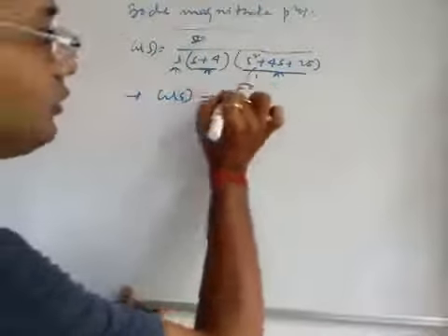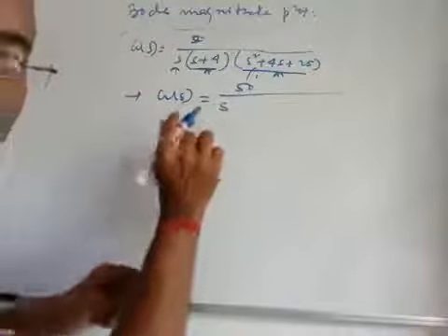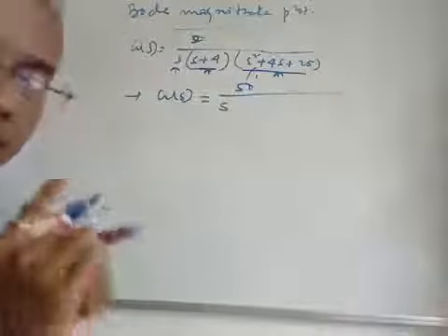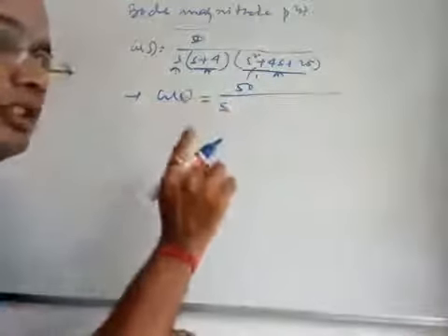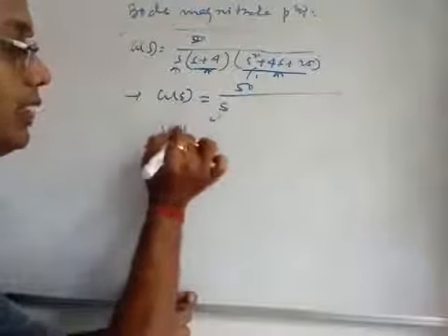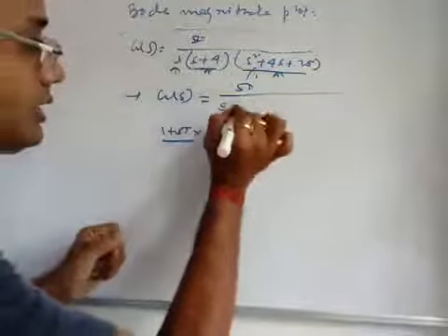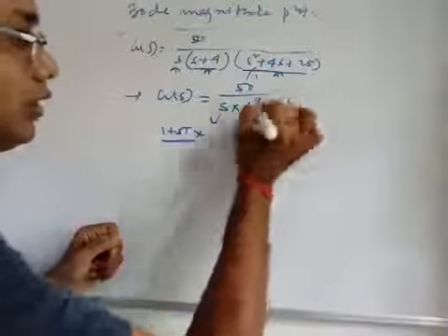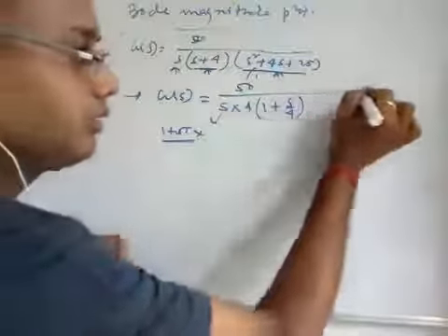That means this is your 50 s. It is not possible to get the 1 plus sT form for it because there is a single pole at s equal to 0. For a structure like s equal to 0, that part always remains as it is, so there is no concept of representing it as 1 plus sT. So this will remain the same. Next, take 1 plus s by 4. Now this has been expressed in 1 plus sT form. You can view it directly from here.